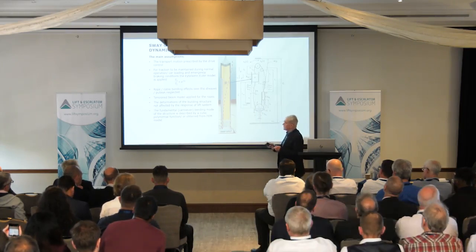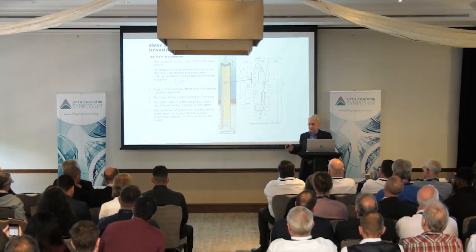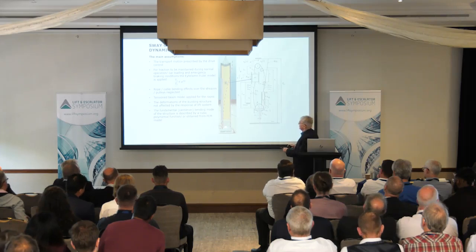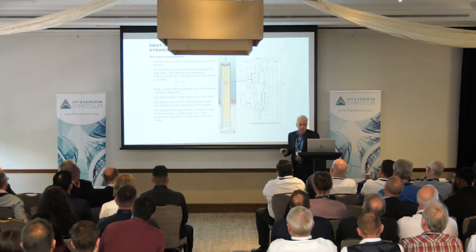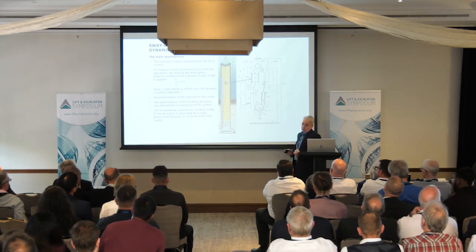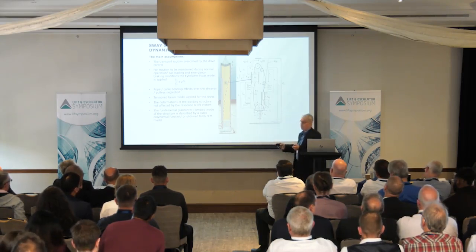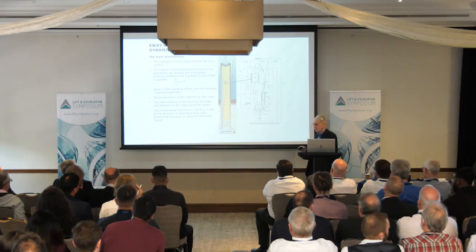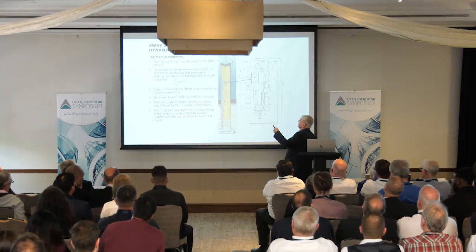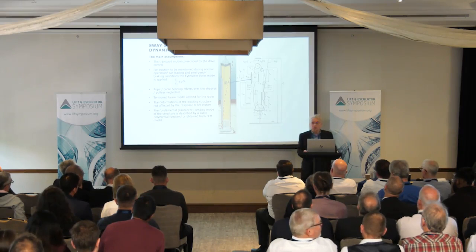This can be approximated by some mathematical approximations. In that case, that's a polynomial, cubic polynomial function. However, in practice, we could do analysis using finite element method. You can get at the design stage of the building the shape of the fundamental modes of the buildings.